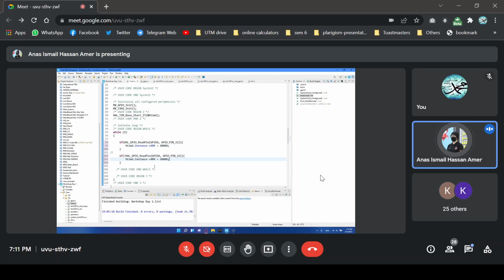If I press the other push button, let's bring it down to 5K maybe. So 5K is going to be a 50 millisecond interrupt. You can recalculate to figure out exactly how much, but I think it's going to be 50 milliseconds. So that's it. Now we can change how fast the timer interrupts while pressing the push buttons. So if you build this one,